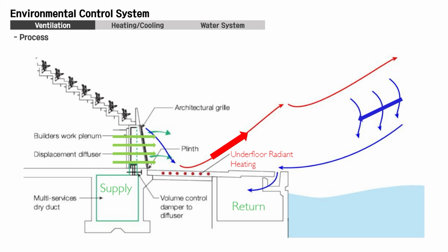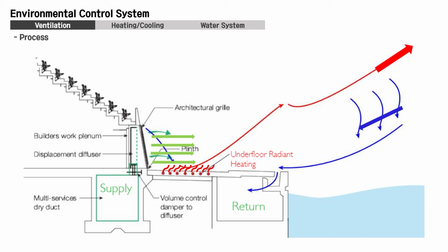To make the best condition for the athletes, they tried to make a fresh air condition, especially for the poolside. This is how it works. First, air is released through vents in the seating wall, and the air is heated by the water-based radiant heating system in the floor. Next, the natural rise that follows allows fresh air to dominate the pool space, while cooler, older air falls and is caught in a return duct, which supplies both water and air.